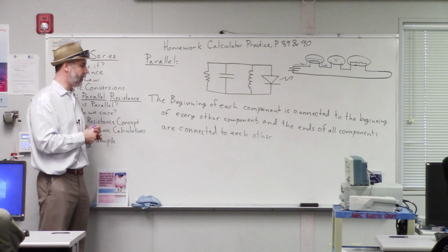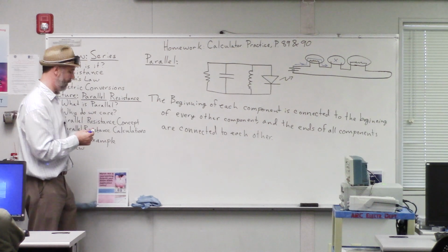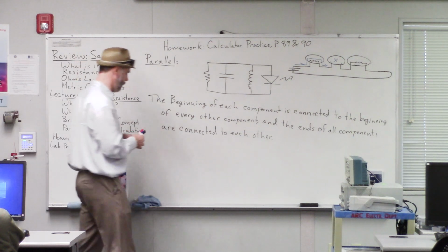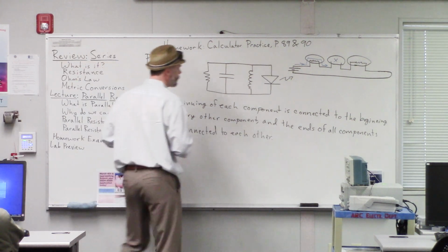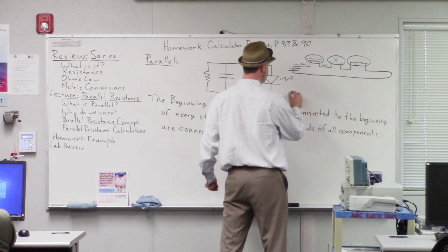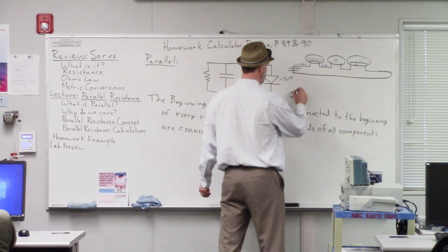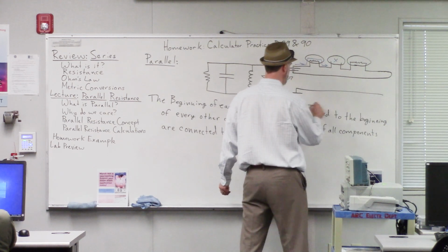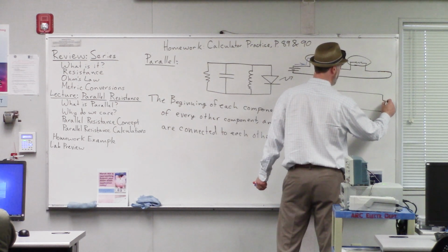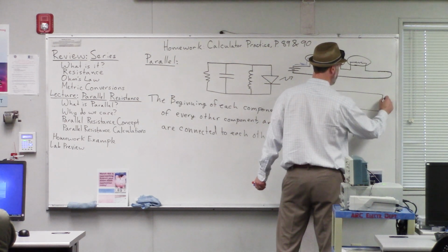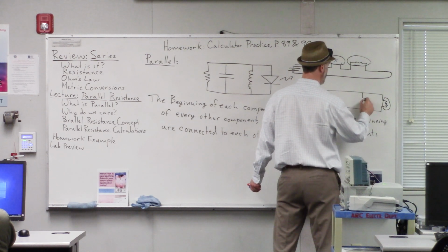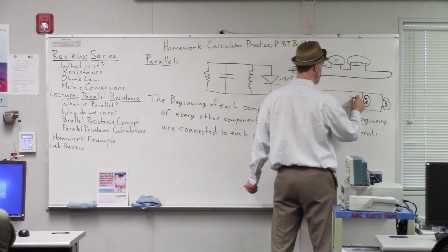But new holiday lights don't have that problem anymore. You know why? That's right, they're wired in parallel. Exactly. So new holiday lights are wired like this. So you have your power supply here, and then you've got these long wires, and your holiday lights go in between. So you have one there, and then one there, and so on, like that.